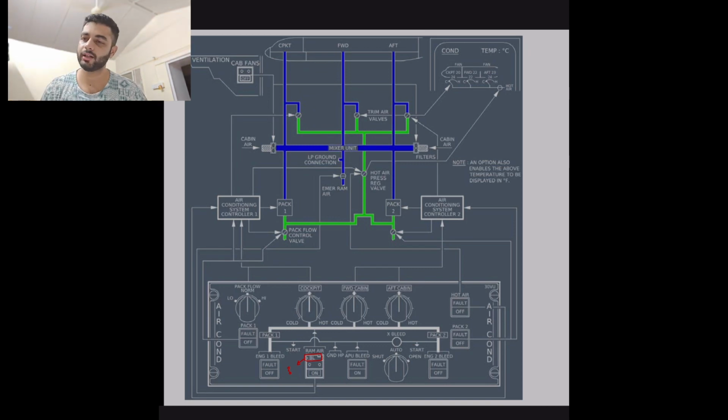Okay, the ram air inlet flap closes during takeoff and landing. The ram air inlet flaps open out in the open and are supposed to take in air. What they do is prevent ingestion of material like gravel going inside, hitting the compressor and breaking it up, or hitting the turbine and breaking the turbine up. To prevent all of that, they close it during your takeoff and landing. So it closes when takeoff power is set and the main landing gear struts are compressed.